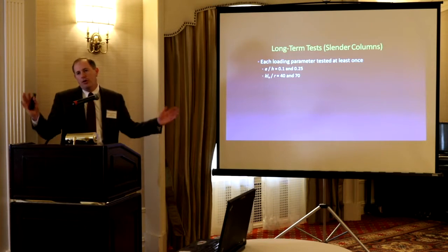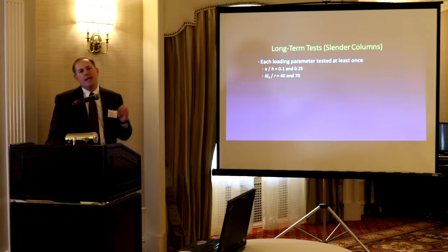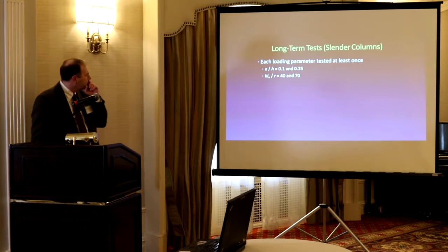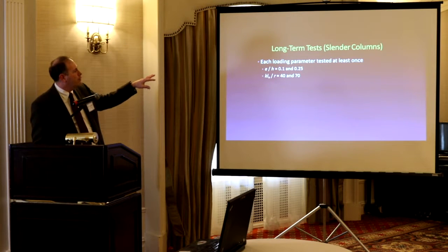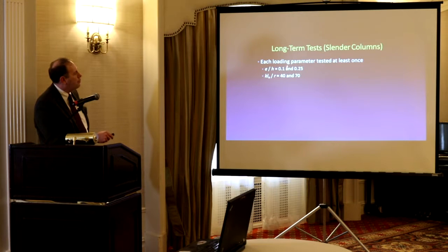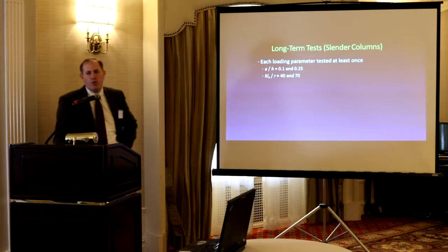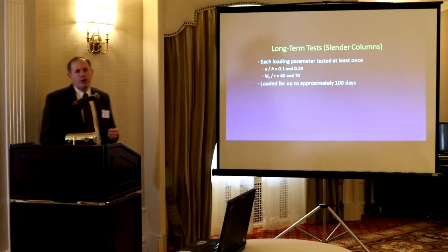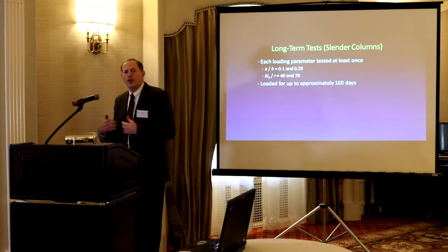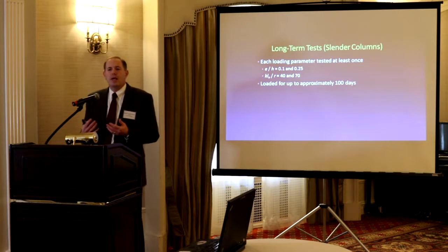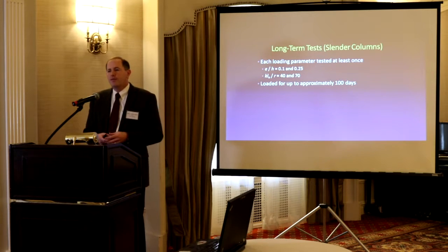Long-term tests, whole other animal. Because I'm sustaining a load, there's creep, and there's shrinkage going on too that interplays. We looked at all these different loading parameters, each once. So we had a 0.1 and a 0.25 e/h. We did two slenderness ratios of 40 and 70. So 70 is pretty slender. We loaded for 100 days, so they were sustained for 100-day loads, which actually is more than what was originally done. The original ones were about 30-some days or so, so we sustained fairly long here.